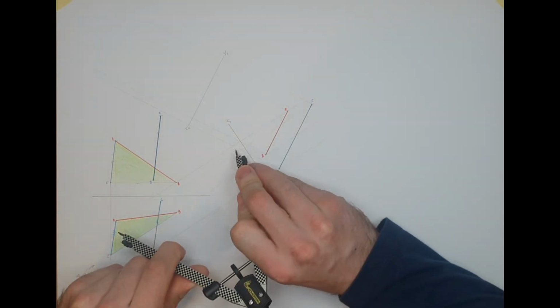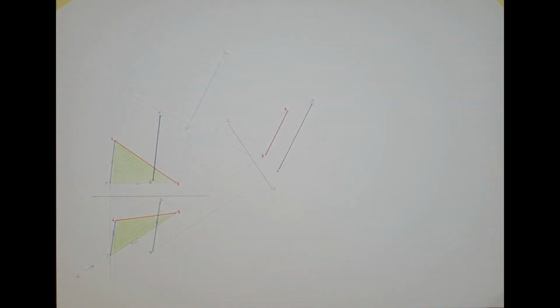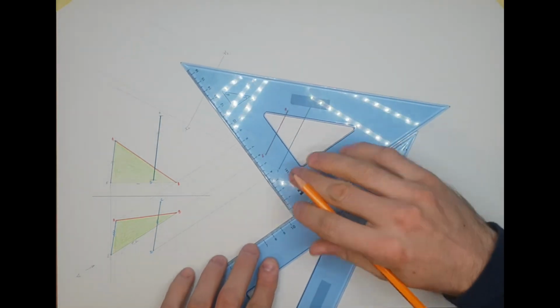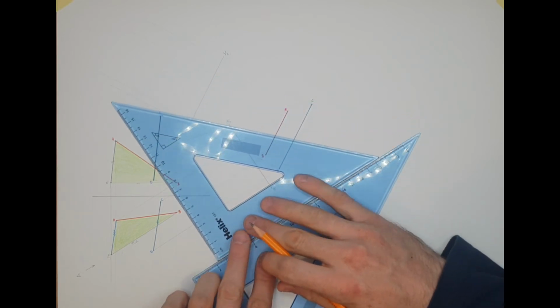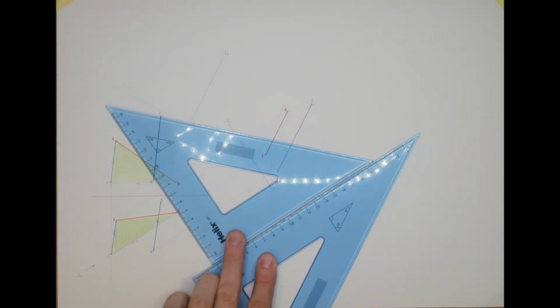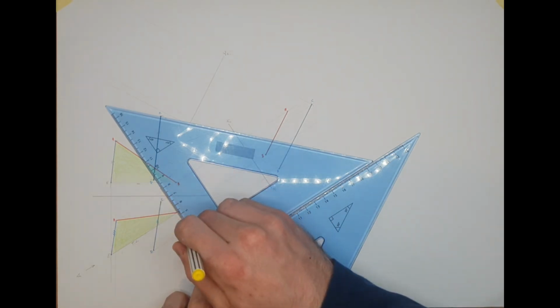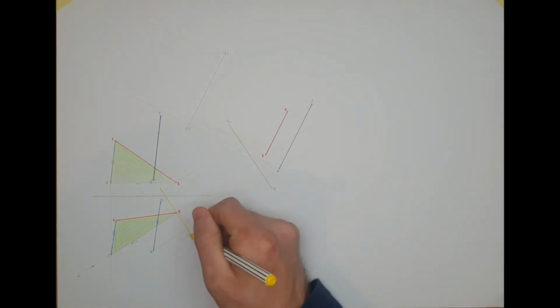Now the largest one there is A, and it's just so big, it might just about fit on the page, but I don't really want my drawing to get that big. So what I'm going to do is take the angle of the XY, and I'm going to reduce every measurement back by a little bit. I might put a reference line in right here on B, in a different color that I haven't used, in yellow here. So that right there is a reference, REF line.